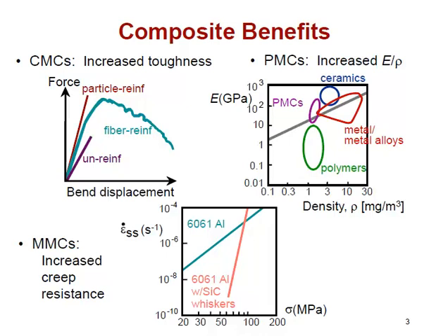And then the failure, this is important, the failure is not abrupt, it's gradual. So from a fail-safe standpoint or a crack detection standpoint, that's very important. We're not going to get catastrophic failure with those fiber reinforcers. So even if we didn't improve the fracture toughness, which of course we did, that would be a tremendous benefit for safety and service.